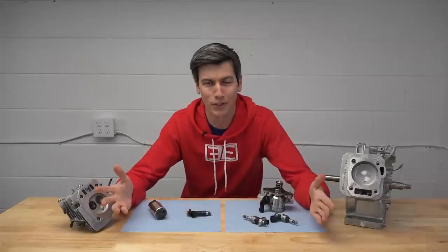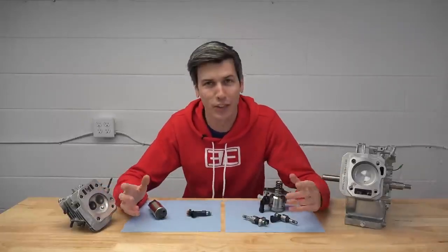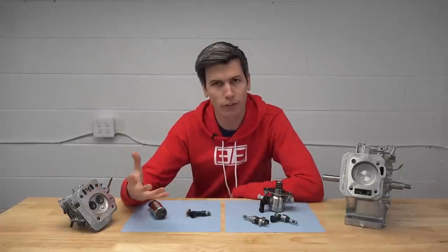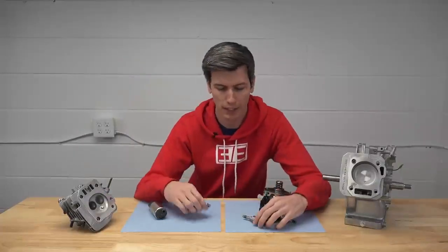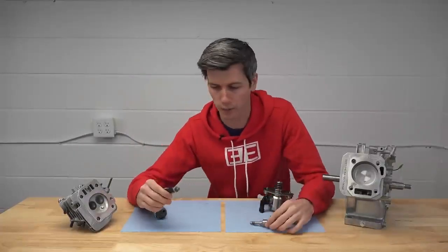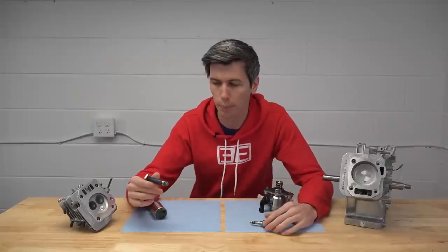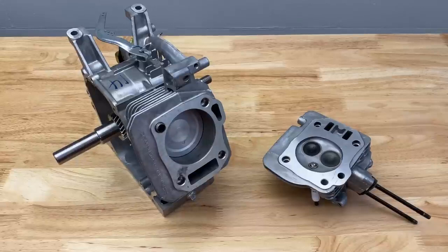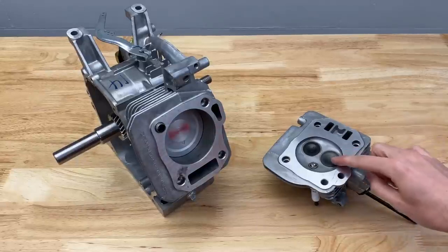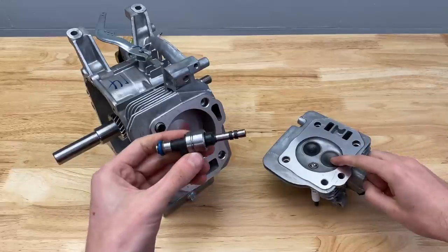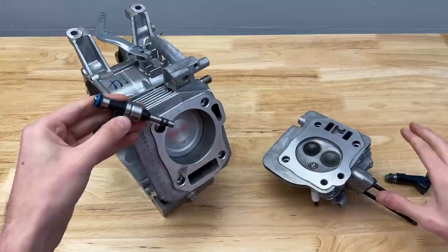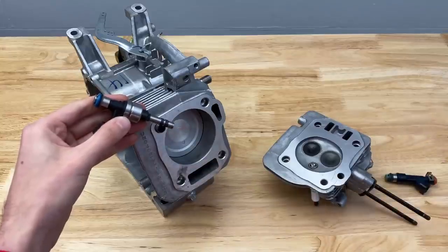So then the obvious question is, well, why not both? And so that's actually what quite a few manufacturers have implemented. And there's a lot of good strategies that you can use by combining both port and direct injection. For example, at low loads and low RPM, use the port injection with or without direct injection so that you have a nice air-fuel mixture going into the cylinder. And then as you get to those higher RPMs and higher loads, you switch over to just direct injection. That way you have that cooling effect occur directly within the cylinder and you can maximize power potential.